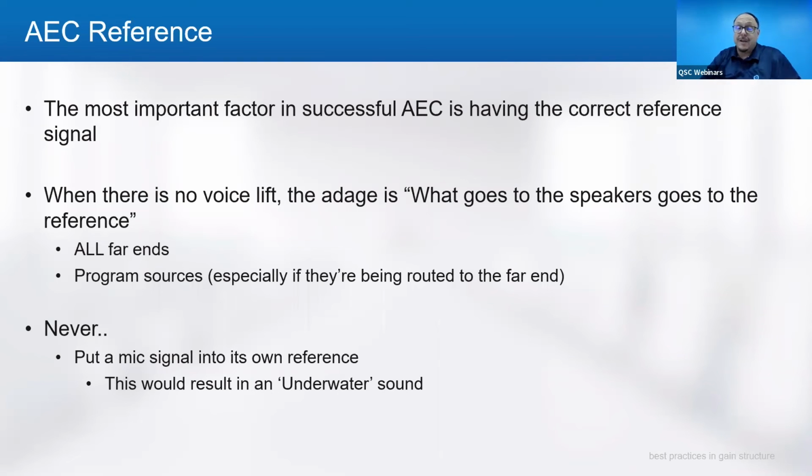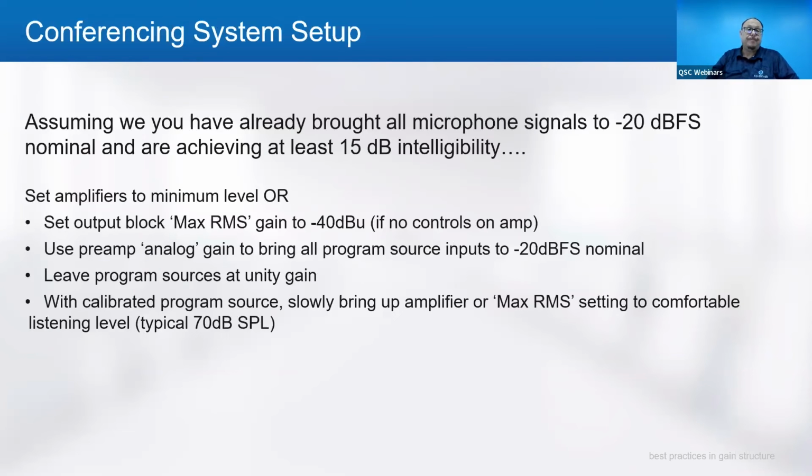If you hear an underwater sound, or if the far end says they hear an underwater sound, you probably have added a microphone to the reference there. Because what's going to happen is, instead of subtracting the program audio out, if you put the microphone reference in there, it's going to try to cancel that out. So it's going to sound really garbled on the far end there.